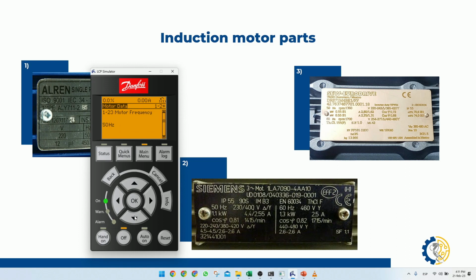So if we go down, it's asking me for the motor current. So we're looking at it on this side, and its current is for 4.5 amps. So we select it, and here we're going to change it to 4.5. 4.5 amps. You see this? So it's pretty simple.